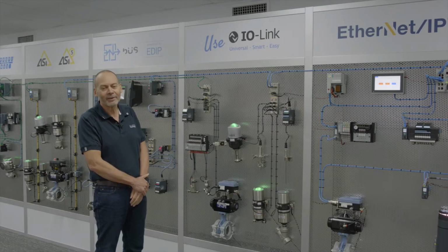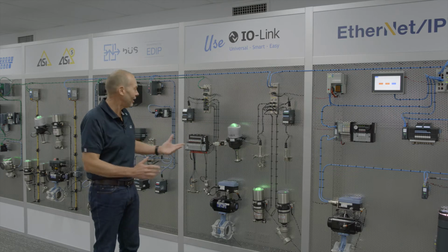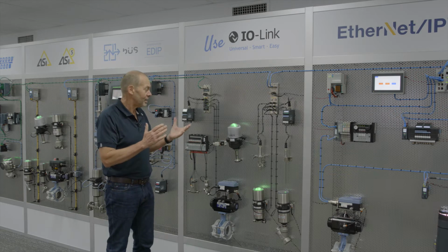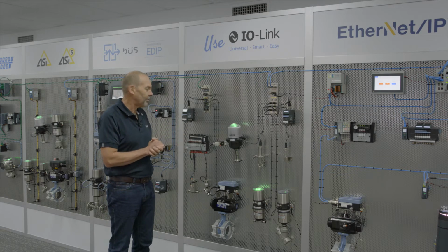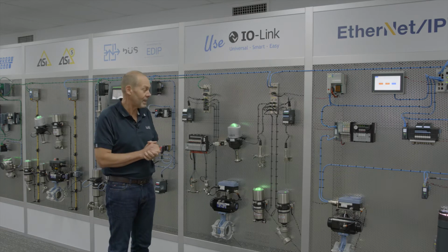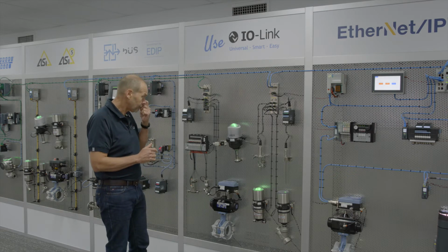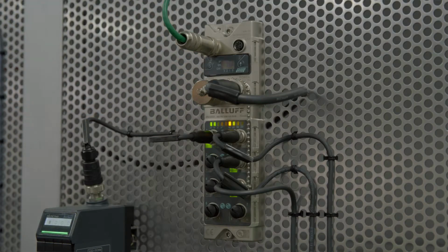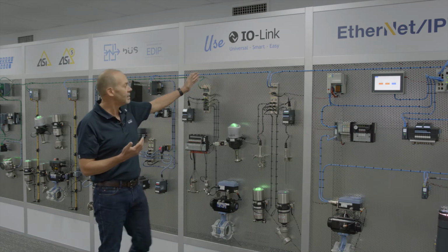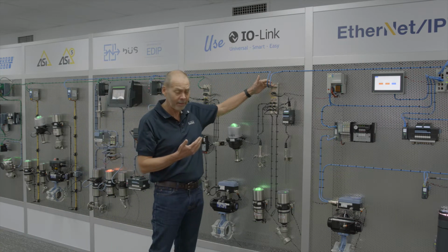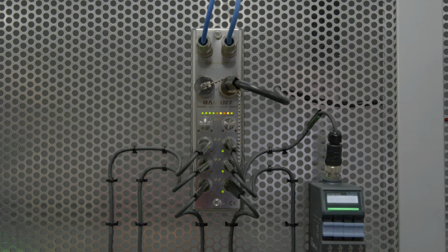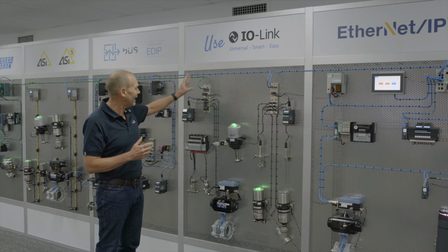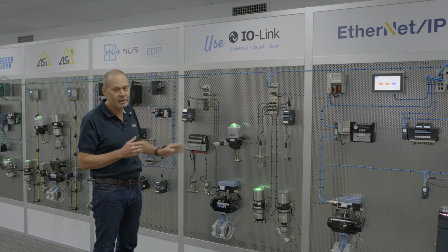Welcome to our digital connectivity video on IO-Link and connecting IO-Link in the field. IO-Link has been widely accepted in recent times simply because it's a very capable and yet very simple network to understand and to deploy in the field. It generally consists of blocks that are talking onto a main network like Profinet in this instance here, or on this side we have Ethernet IP. It could also be Profibus, CC-Link, or other networks. So it's a sub-network where we actually link these field networks to individual devices.